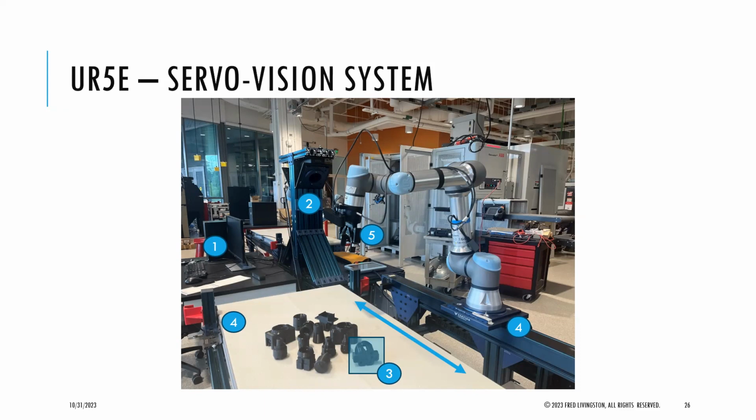All right. So when you try to move the arm to a position, we first need to calculate the forward kinematics and then do inverse kinematics to figure out the angles. Yep, so you're doing the forward and the inverse kinematics. You can use the DH approach, or the kinematic chain, or whatever to get that, but you need to do the forward and inverse to solve the complete problem.